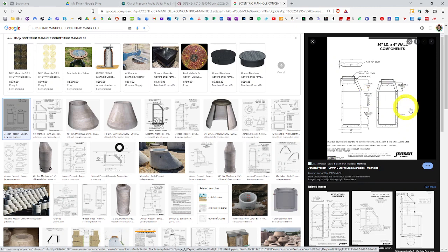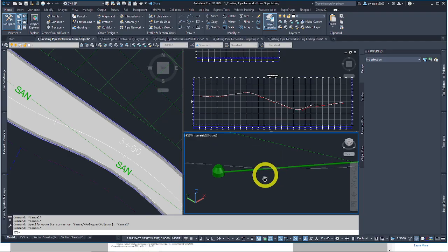They're oftentimes precast concrete, bought from a local source or an area in the region to easily transport these large objects to job sites. They come in various different shapes. Manholes, here's more of a cylindrical shape all the way up. A lot of them have an eccentric top like this. Here's one with a few inlets and outlets. Just to give you a quick heads up on what we are talking about with pipe structures with gravity networks. So we go back here, you can kind of see it looks like that in the 3D view.